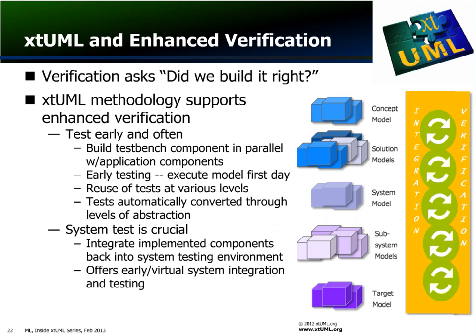Thorough requirements verification is a key theme of any safety critical flow. Earlier we talked about the confusion between validation and verification. We said validation was determining if you were going to build the right thing, which required a review of requirements. So verification is ensuring that you are building the thing right. In other words, it ensures that the requirements that earlier during validation had been deemed to be the right set of requirements have been implemented properly in the design.